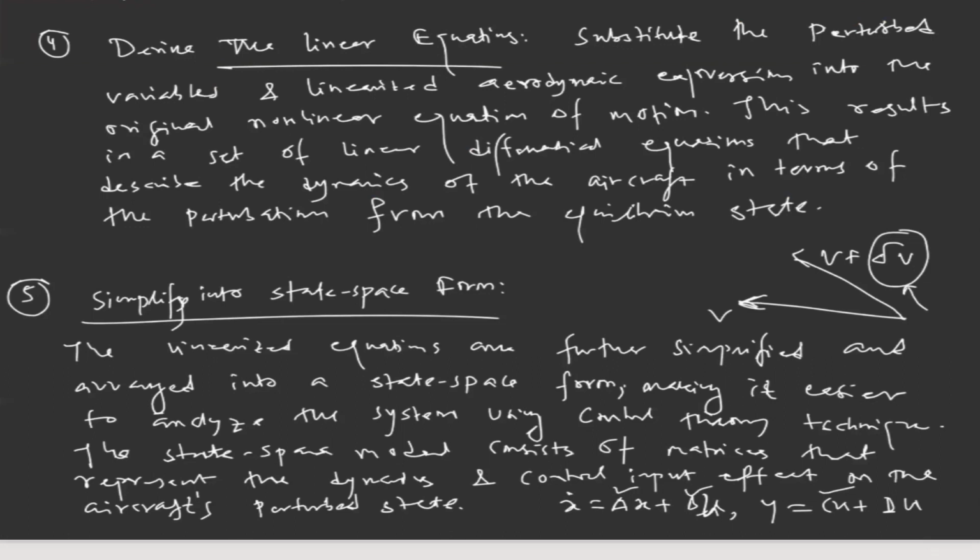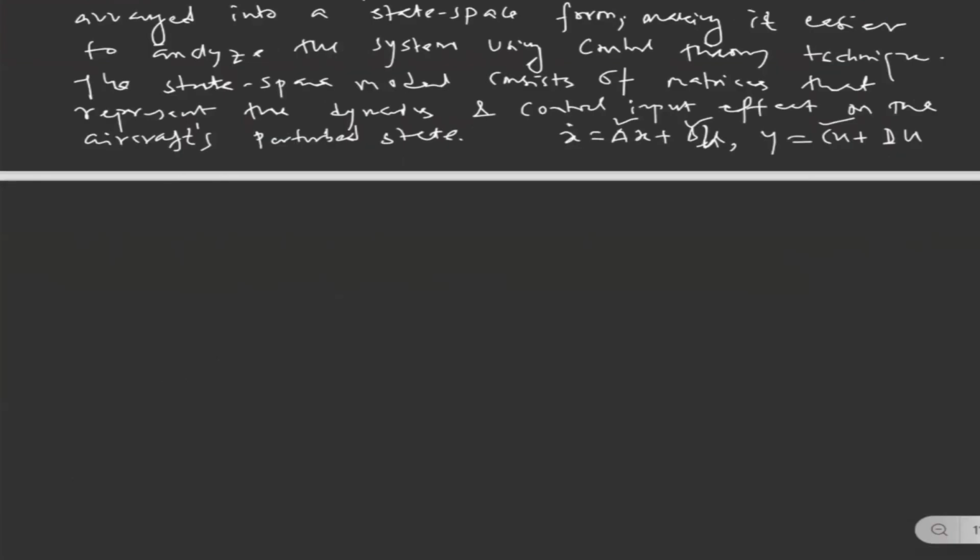Now we'll take our system. The first system we are going to take is the longitudinal motion, and how we can apply this perturbation theory to come up with the linear model of the longitudinal equation of motion of the aircraft. Before that, we need to apply the perturbation to all variables and write them as part of the reference states. So let me write.